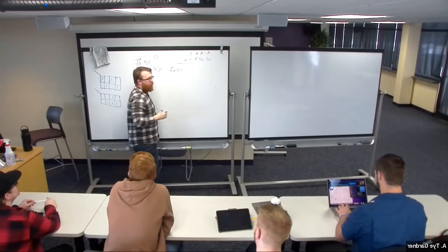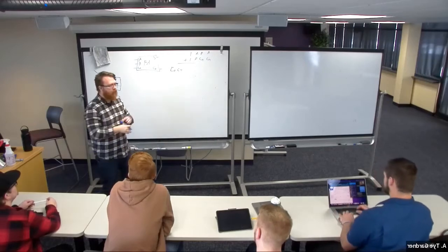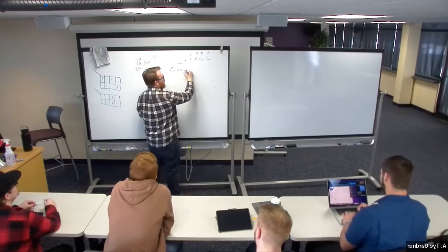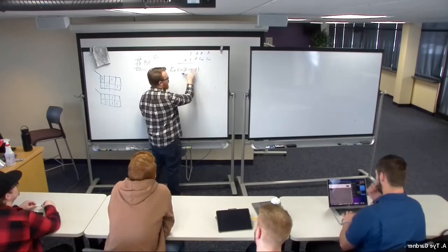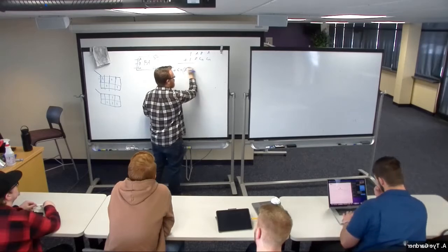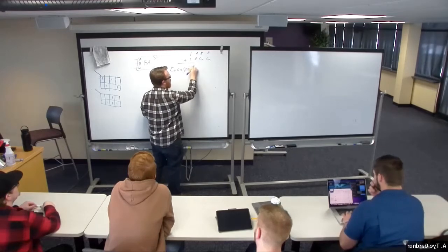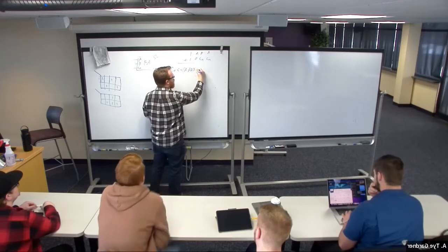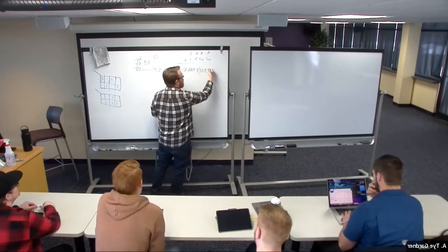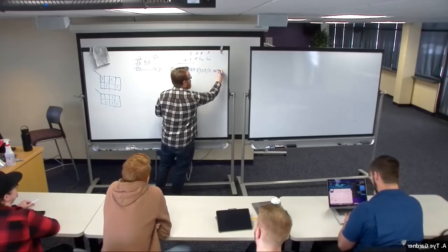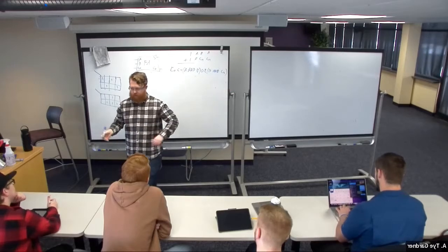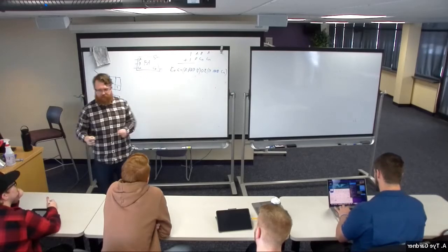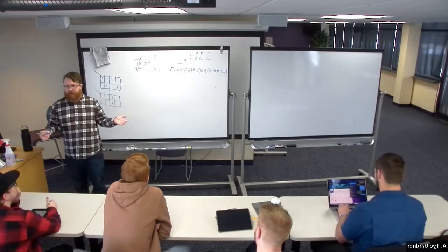CO gets assigned to, right? This is an assignment statement that we're going to get back to thinking about, and say it is A and B. But if we're in the HDL, we need the and, right? A and B, or B and C in, or the other one, A and C in. And if I write that, I'm done. I've designed the carry out circuit for my full adder.